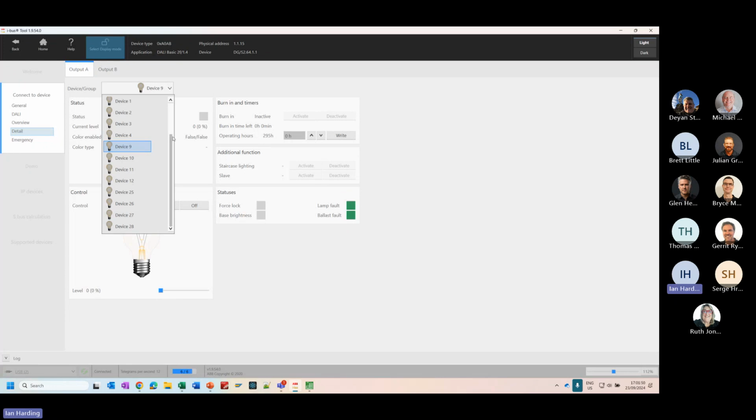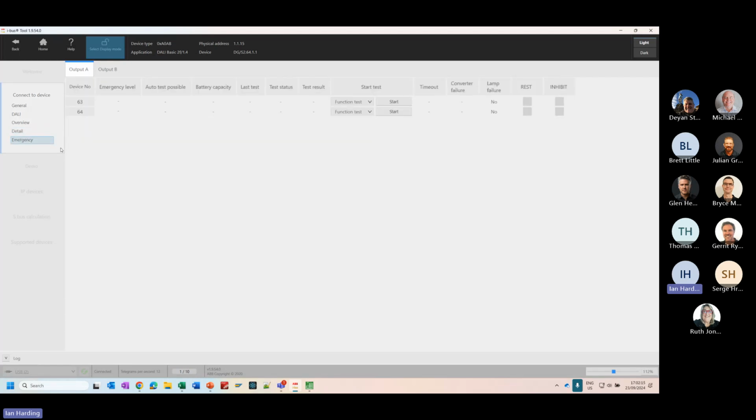And if we had the premium DALI gateway, I could go in here and I could change colors on the fitting, and I could set the color to whatever I need it to be. I could take the hue and the saturation. I could look at all those values, and I can change the color of my lights here till I find what I want. I can remember the settings and set that into maybe a scene as well. So, it's really helpful for sort of stuff like that. When I look at the emergency lights then, it queries the emergency ballast.